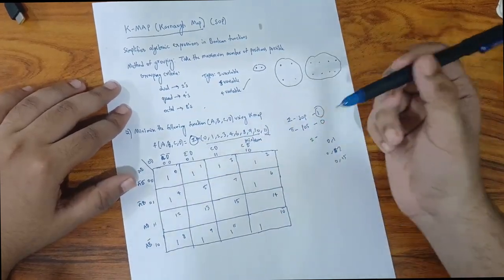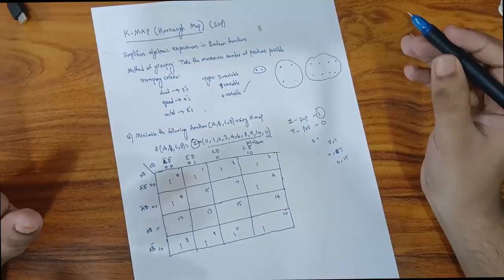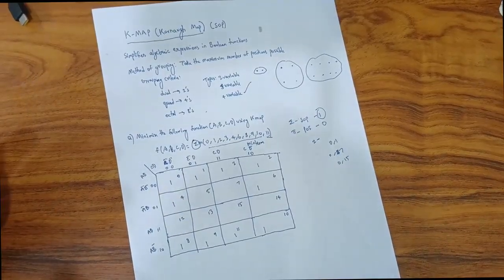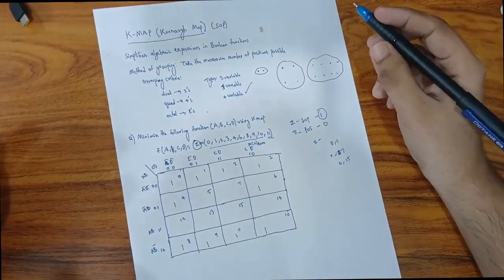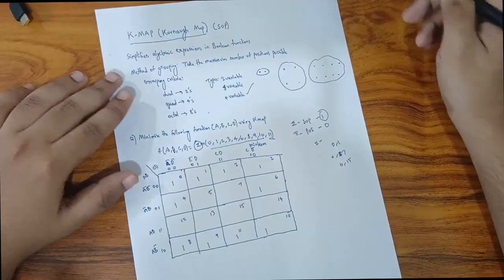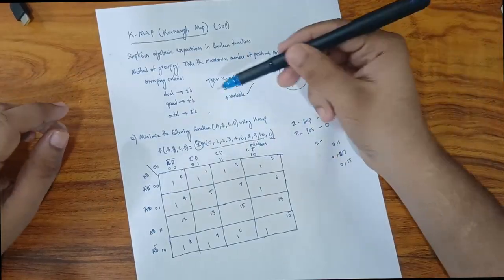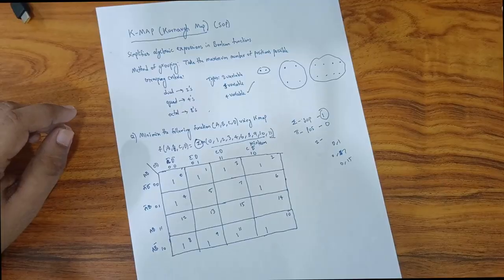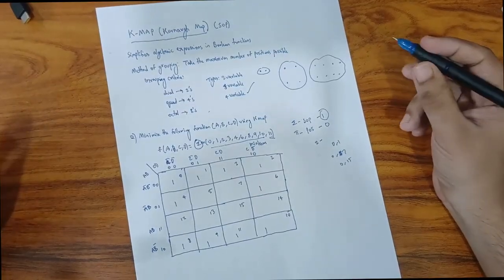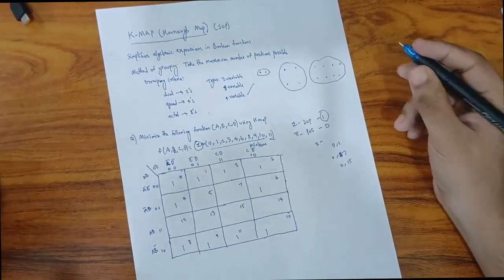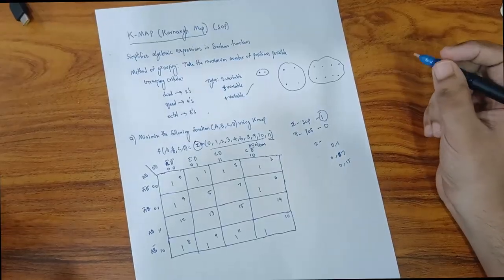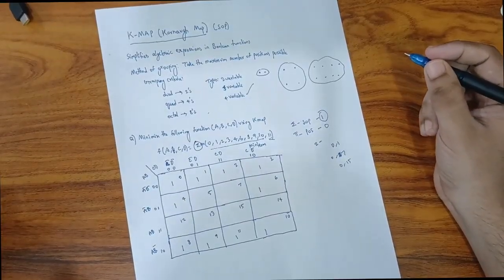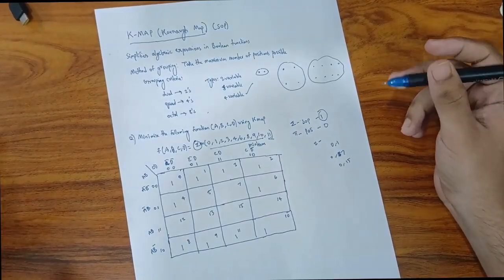Okay, so we managed to write the minterms of this kmap, and this is how we fill the kmap. I think you got the gist. Now what we need to do is the grouping, and as I already told you, we have three criteria for the grouping: dual, quad, and octal. In every grouping method, we need to take the maximum. We need to group the maximum number of minterms possible. So let us look at the minterms right now.